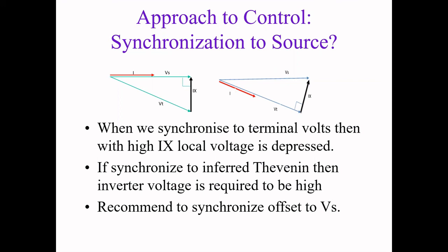Last question to Gerard. I see a lot of utilities are using a fault level to assess the weak grids, to assess how much solar farm or wind farm you can build in there. So can you elaborate on your understanding of the short circuit ratio, and if your control approach could actually loosen those requirements, because you are inferring those voltages further away or using broadcasting signals? So does that mean we could actually loosen those requirements?